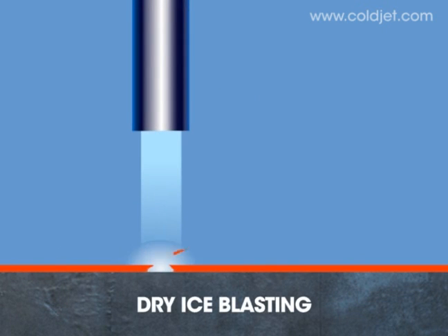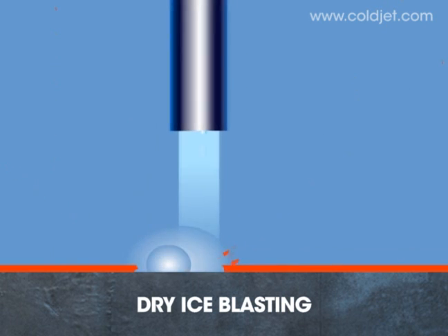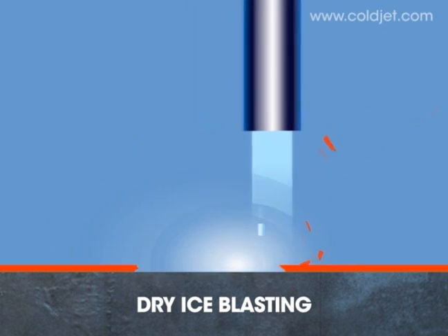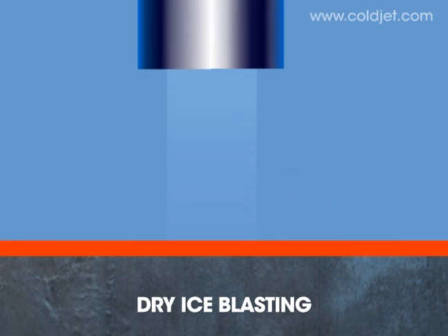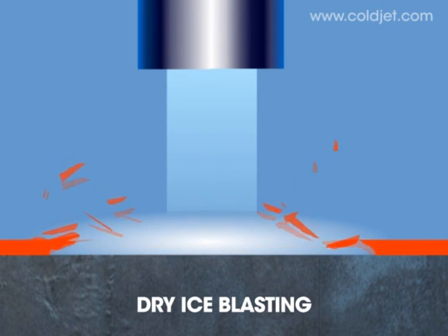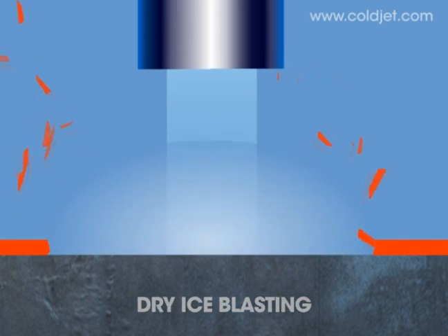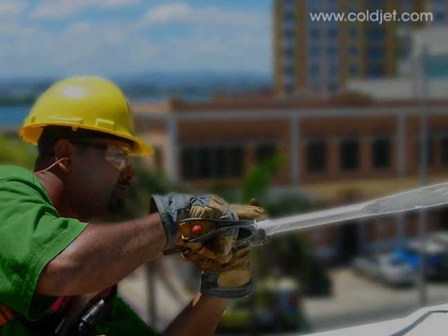Dry ice, on the other hand, disappears as it cleans, and will not alter most industrial substrates. On successful cleaning applications, the dry ice pierces the contaminant, but sublimates upon striking the underlying substrate. The resulting expansion of the carbon dioxide gas actually lifts the contaminant off from the inside out. The dry ice then disappears without damaging the targeted surface, and without creating grit entrapment issues.